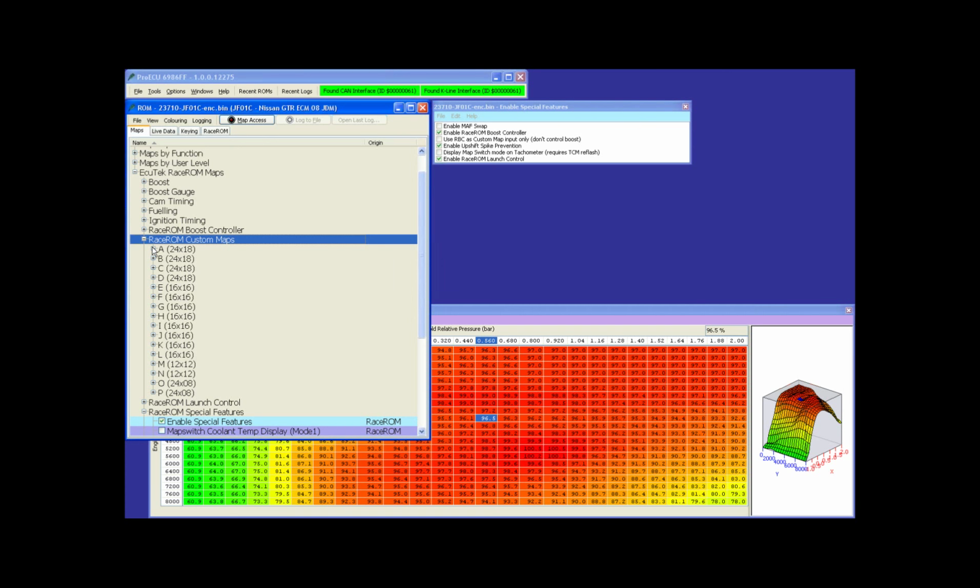but it is a complex boost control strategy, and sometimes, being a tuner, you just want to get the car set up as quickly as you can, and you don't want to be concentrating on 3 different things: ignition, fuel and boost control. So by using custom maps, it's very quick and easy to hard code some simplistic boost control.